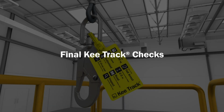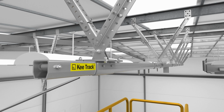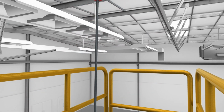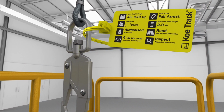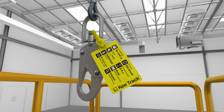Final Kee Track checks. The Kee Track installation is now complete. Complete the Kee Track system tag and attach it in a position that is permanently accessible to the user prior to attaching to the system, or directly to the personal fall protection equipment that connects the user to the system. Prior to first use, a final inspection of Kee Track shall be undertaken in accordance with the examination scheme detailed in the IFU.